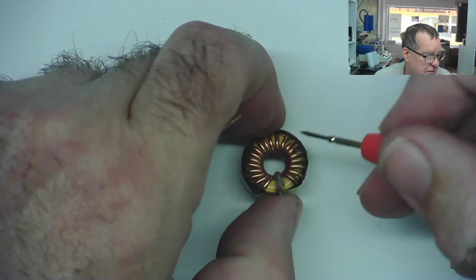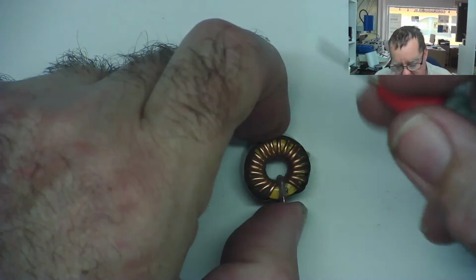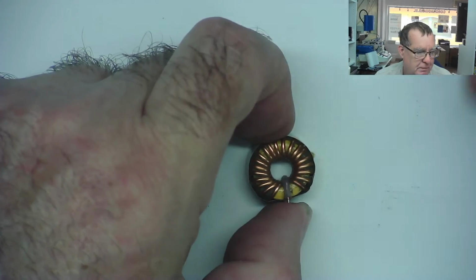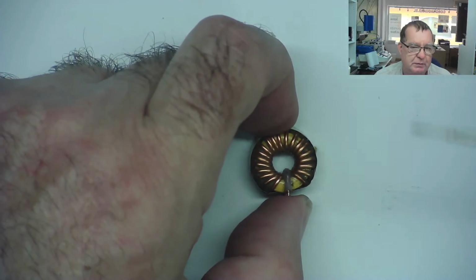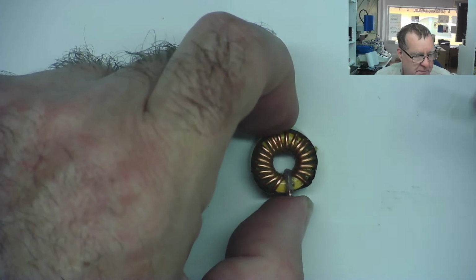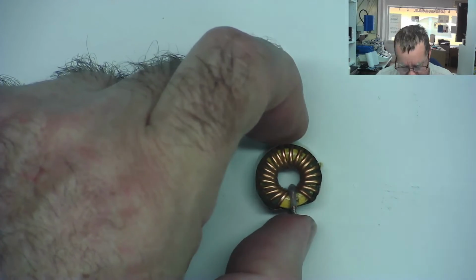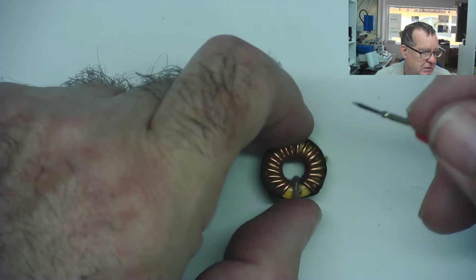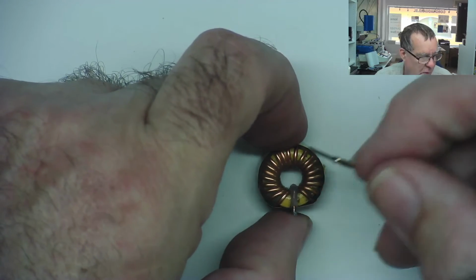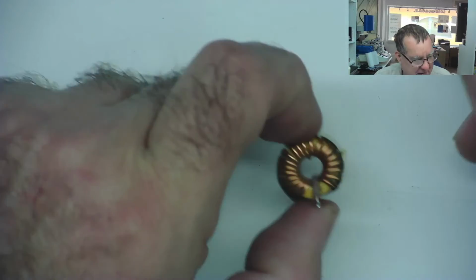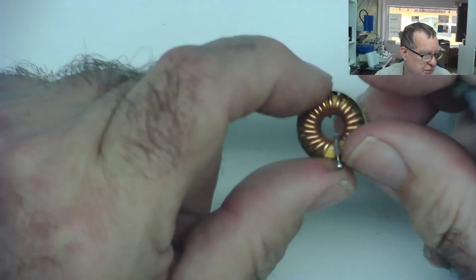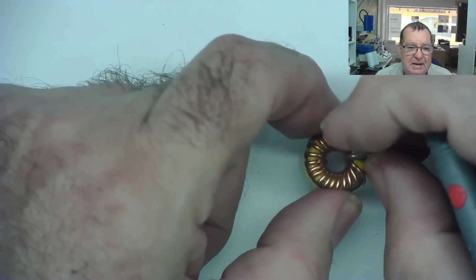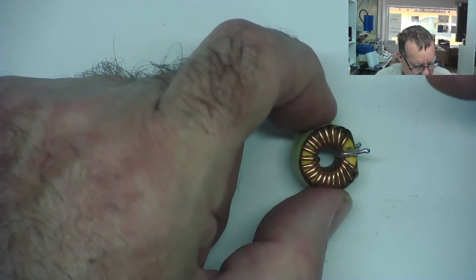If you get an inductor that is smoking or something like that, you can pretty much say it's because there's too much current passing through it. It's not smoking because there's something wrong with the inductor. It's smoking because there's a short circuit on the circuit it's providing, and the power supply coming in is capable of producing a very large amount of current, enough to get the wire so hot it will smoke. You'll see it on larger inductors with many, many more turns, not things like this, but if you see that, it's a short circuit that's causing it, yeah?